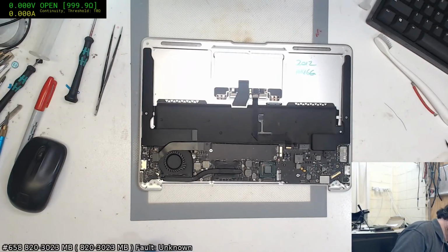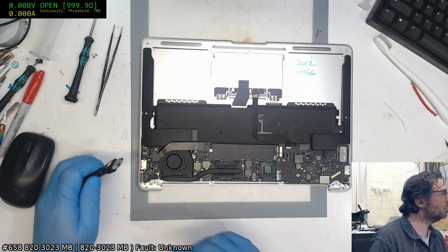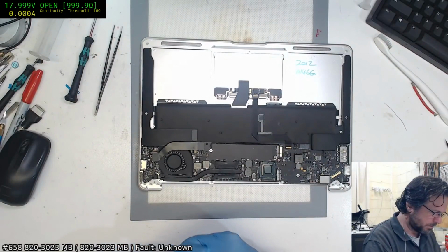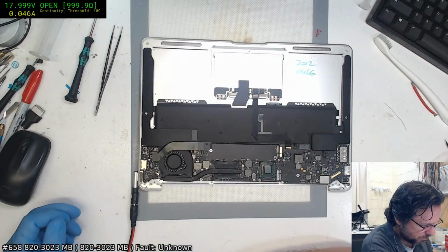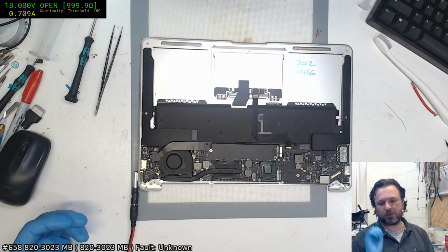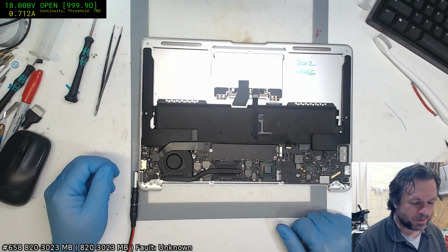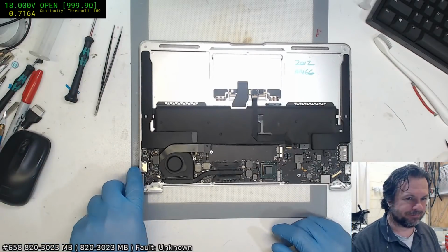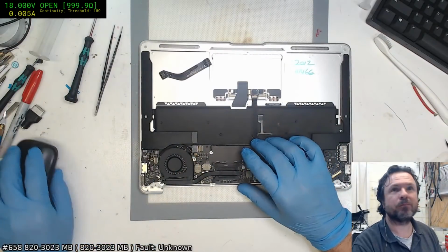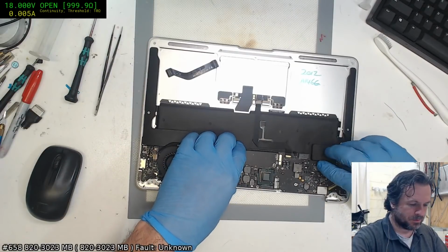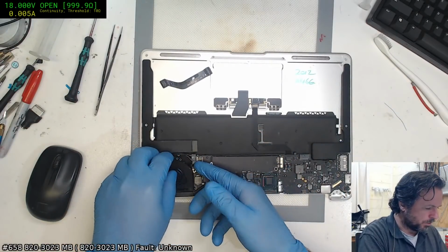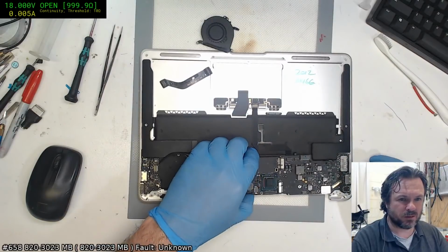Okay, put a chipmunk in. Are these MagSafe 1 or 2? MagSafe 1. Okay. Well, that boots. Okay. This is the classic problem with these boards. The 3 RAM beep. Yeah. 3 RAM beep. Okay. And I hate to say it, but once you get the 3 RAM beep, it's probably not really worth doing much more. Just swap out the RAM.